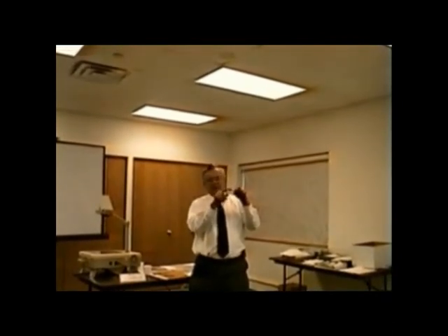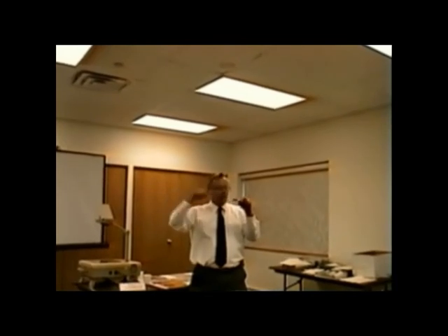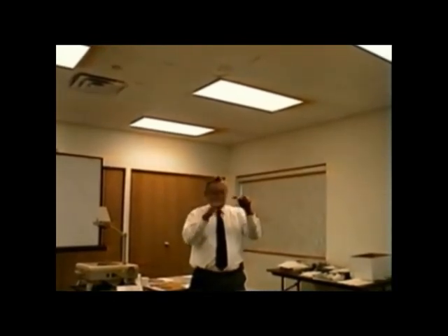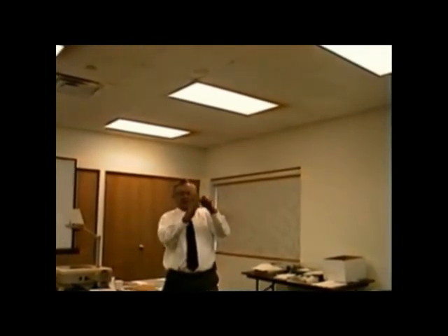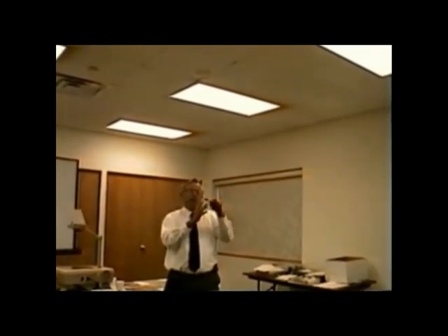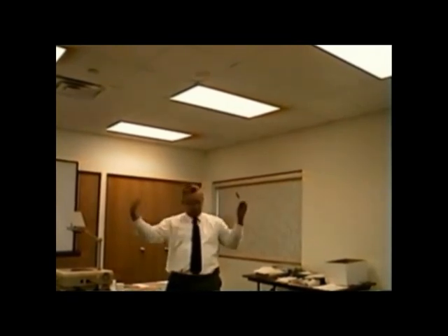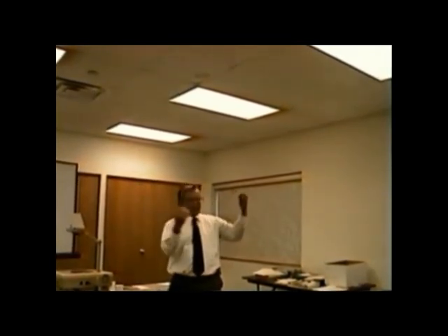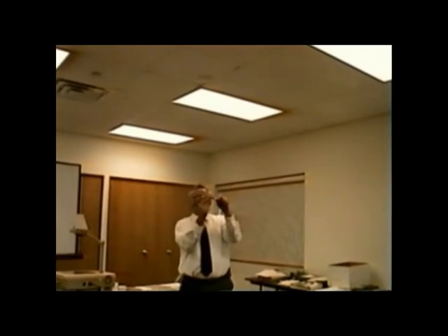Well, if we put 24 volts on the flame rod, we actually have an AC 24 volts available on the flame rod, which is the flame sensor. We have the burner down here, and once we have fire, the fire becomes a conductor for the flame rod. So between the 24 volts and the burner ground, and the ground is the gigantic ground, which is the furnace and goes back to the conduit or the Romex wire, but that's a gigantic ground and a very teeny tiny tip on the flame rod.